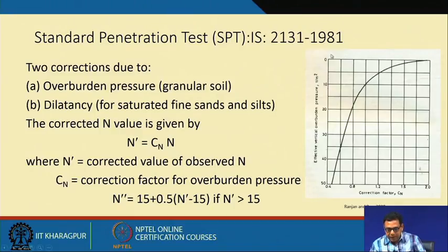This is the effective overburden pressure. As I mentioned, how will I calculate the effective overburden pressure? The overburden pressure means the unit weight of the soil into the depth of the soil at the point where you are calculating that pressure.